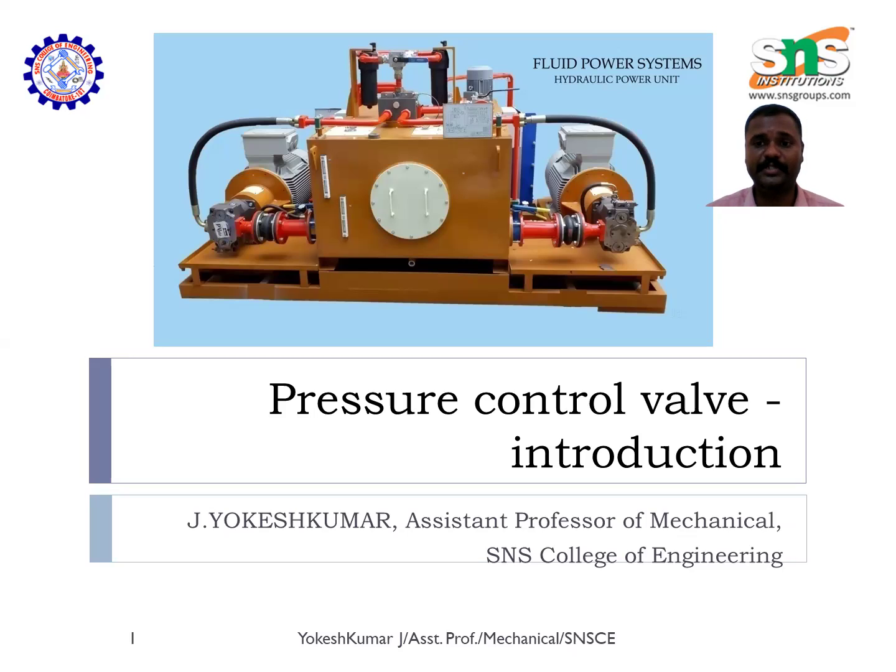The pressure control valve is quite different from the direction control valve. Pressure is an important parameter in the fluid, which is directly related to force. By controlling the pressure, we can control the force of the actuator, because pressure is proportional to force. Pressure is nothing but force applied per unit area. So various things can be achieved by controlling the pressure of the fluid.